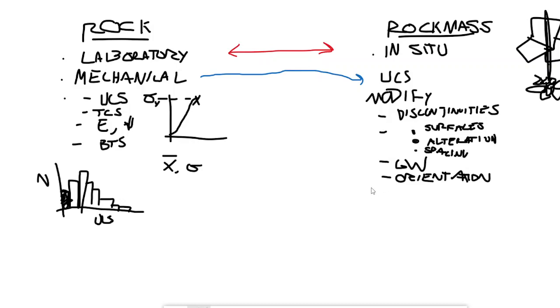And here's where, like I said, it becomes much less scientific like over here in rock, and much more empirical and data driven. You'll have these systems that basically err on the side of being very conservative most of the time. So you'll see ones like RMR, the rock mass rating system, and another popular one is the tunneling Q index, which I believe the Q stands for quality.